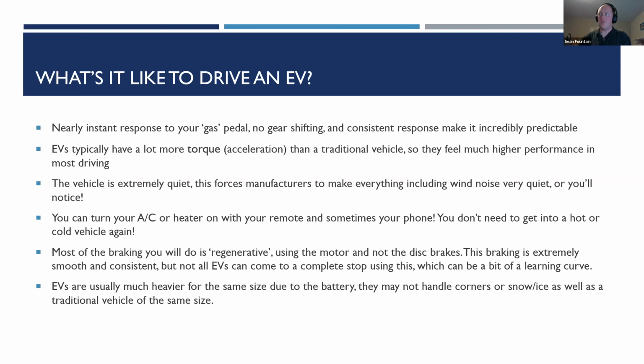Yeah. So different vehicles have different strategies, or different manufacturers do. The Chevy Spark that I owned and the Chevy Volt had this low selection. So you had a gear selector just like an automatic, and it was like drive or low.